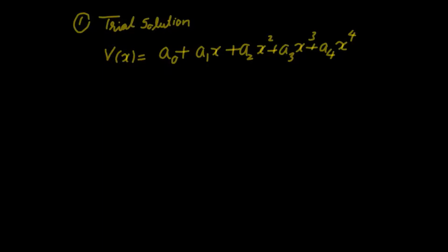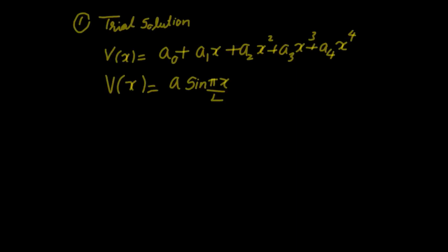Okay, that's good. The next obvious question is, in the previous problem, we solved this problem of a simply supported beam subjected to uniformly distributed load by assuming a trigonometric trial solution, which would be something like sine pi x over L. The reason for assuming a trigonometric trial solution is that the beam mimics a sine wave. So that is so appealing.